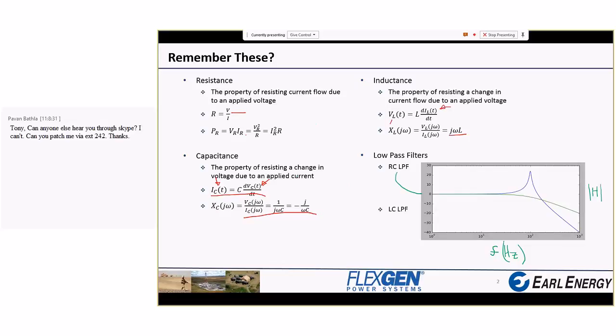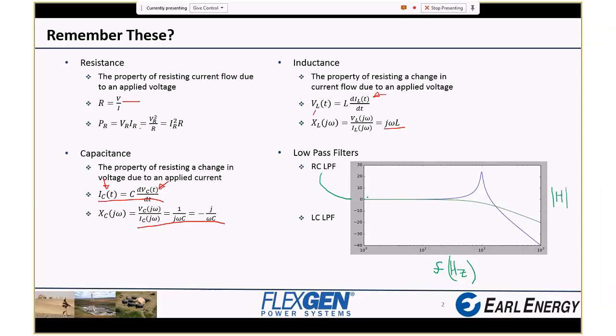These low-pass filters pass signals at low frequency. There's no attenuation. That's what 0 means on this scale. I really shouldn't have introduced decibels just now, but too bad. 0 means no change in the signal. A positive number means it's amplified. A negative number means it's attenuated. So there's no change at low frequencies, and the RC filter comes down here with a corner frequency of 100 hertz, starts to roll off, and attenuates high frequency signals.